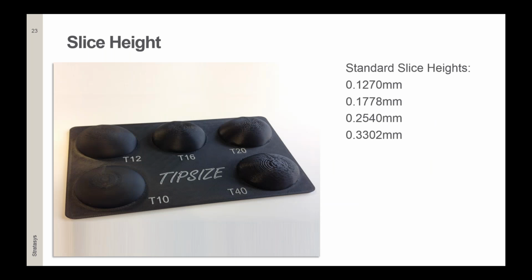We have 4 different slice heights to choose from, depending on the requirements for the part. They will influence printing speed, surface quality, and, in some cases, strength of the part. If your model requires post-processing, such as sanding and painting later, you would like to have it printed with the finest possible slice height. It will increase print time, of course, but it will save a lot of manual work while sanding and trying to hide those layer lines.